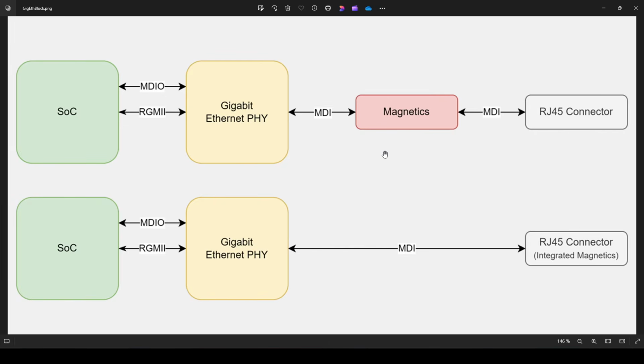On the right-hand side, we have our interface, very simply speaking, connected to the outside world via your typical Ethernet cable. We have two different sets of interfaces on the left-hand side, and we have one interface on the right-hand side. On the left-hand side, for Gigabit Ethernet we typically have a media independent interface, or MII for short, and for Gigabit Ethernet, that's GMII, Gigabit.